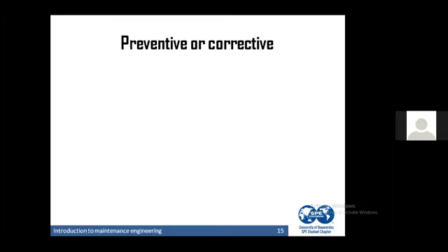During this week, the mud pump, I don't know if you know the mud pump, failed. The people there didn't invest in preventive maintenance on these pumps. And during a whole week, the whole rig didn't work. This is a loss of money also. Not investing in preventive maintenance is also a loss of money.